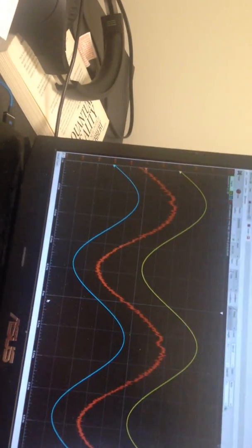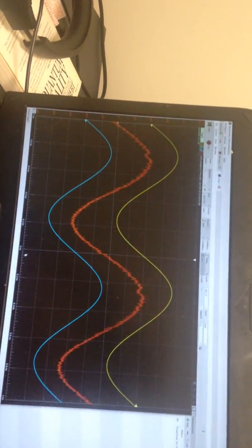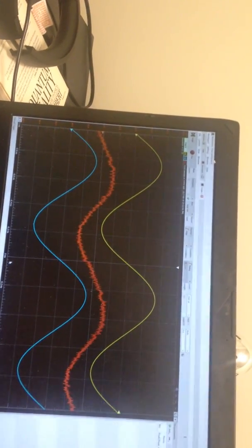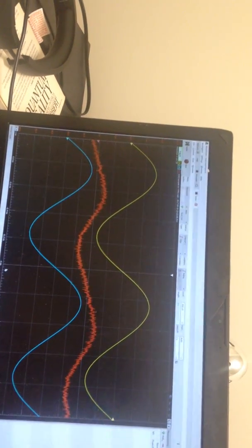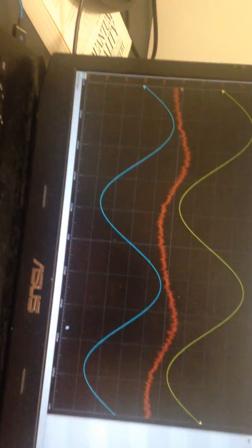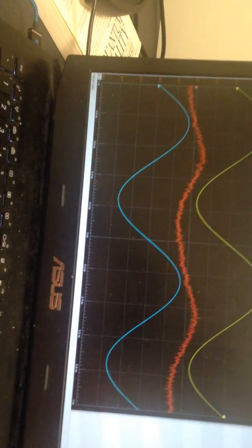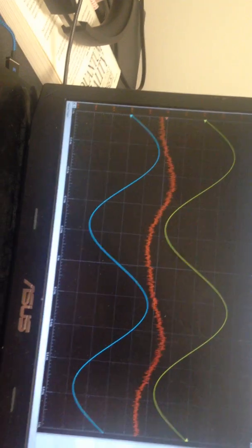Okay. So if you just saw the waveform, you can see how by changing the resistance value you can get it very close to zero, which is actually pretty close right now even, but you can balance it out here. And the averaging effect is already on right now, but you just have to go into time and set the average to 20.